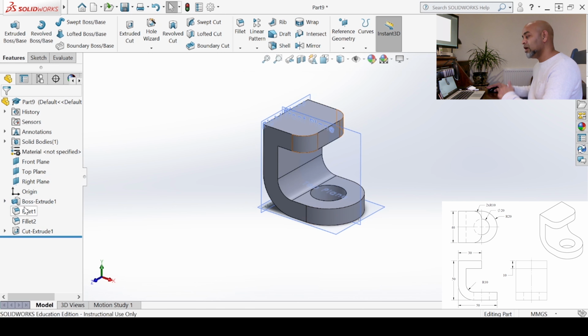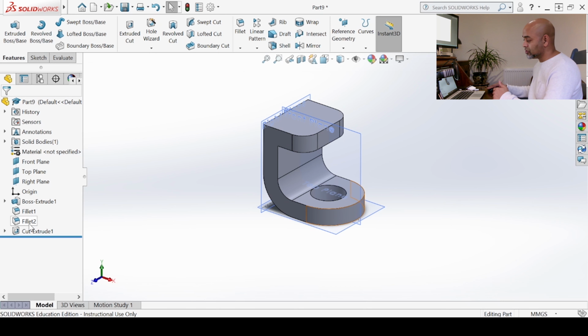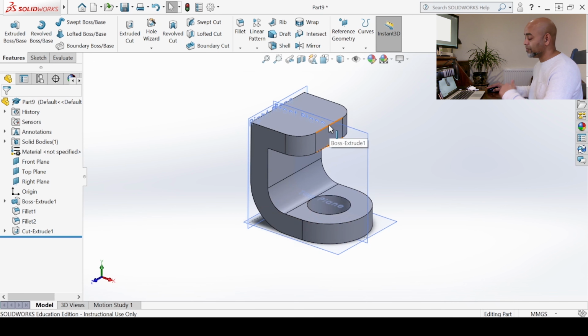Following that, we came in. Ideally, in a professional world, you want to do the cut before you do fillets. Fillets and chamfers are left for the end. We apply them in the very end. I was hoping to use that roundedness as a concentric relationship with that circle there, but I didn't have to. That midpoint gave me the correct spot to do so. But I could have organized them at the end as well. So that's a better practice to do.